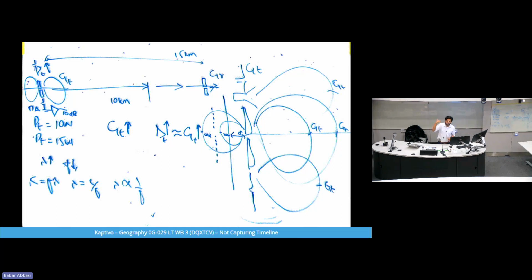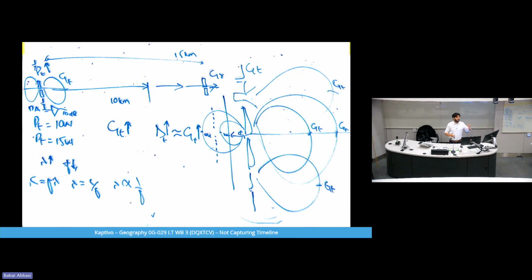Also, we can increase the transmit antenna gain and increase the receiver antenna gain, and both can be done by just removing very bad gain antennas and adding some very good gain antennas, or gain antennas that we actually like. Okay. And there is another method that's called antenna arrays. So we can actually increase the number of antennas to do the job for us, or help each other to throw energy in the direction.